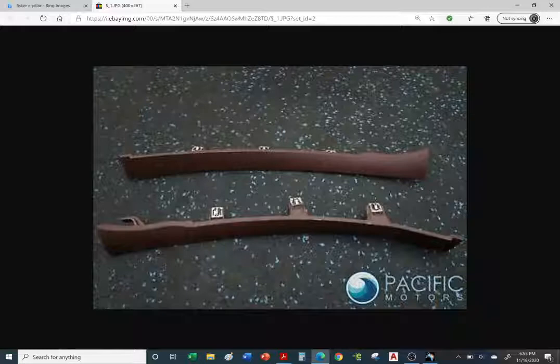You can just buy these clips from a catalog, and they clip onto the structural member of the A-pillar of the vehicle. The issue was that these towers were just way too tall, and it was causing the A-pillar plastic piece to stick outward. I was asked to shorten these towers for the next model. We're going to leave everything the same, except take these towers, make them shorter, and reattach the clips. We would have to alter the tooling for this piece to get a better fit and finish on our vehicle.